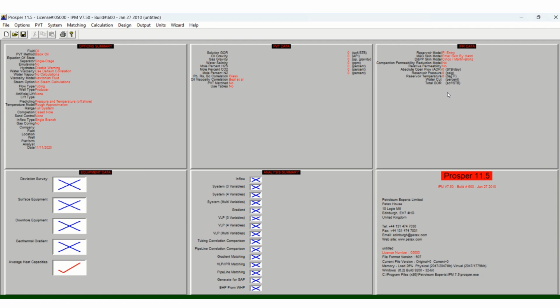So when we start entering data by tomorrow, you'll see how it works. Now this IPR data helps us to plot our graph. There you will see the AOF, which is the absolute open flow. You'll see the rates at which it's producing at AOF. That's the highest possible rate a well can produce. It is actually an ideal value.